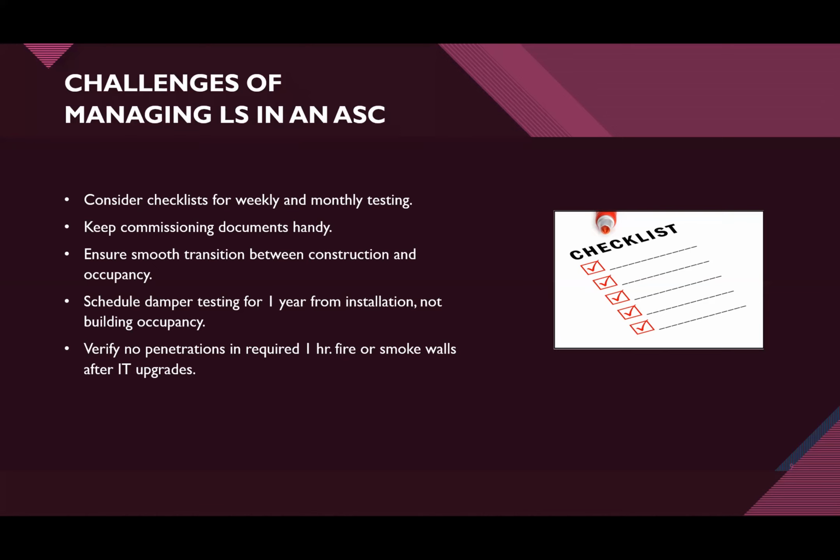You want to make sure that all of your outlets are tested when they are installed. GFCI, hospital grade, regular outlets. When the building is built, you need to have those all tested. So you're checking for polarity, you're checking for grounding, and you're checking for the resistance of how hard it is to pull the plug out of the outlet. All right. And so when I go and I say, so where was the blessing of all of your outlets that are in the facility? And people don't know. And then when you talk to the construction people, they don't know. And then it's a finding, and then you have to go find it. So I'm just saying, consider keeping those documents all in one location that are readily available.